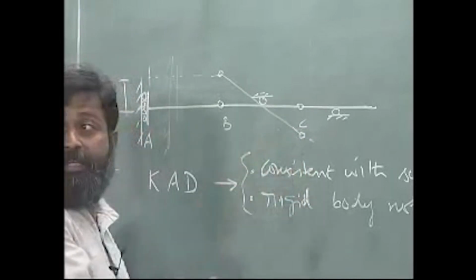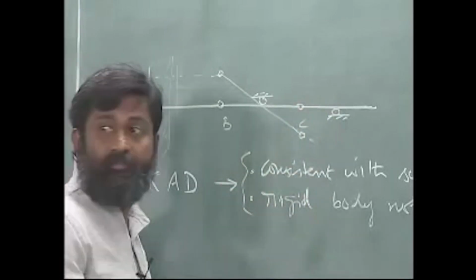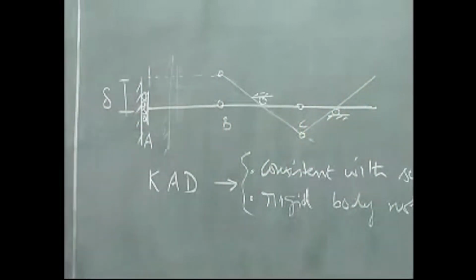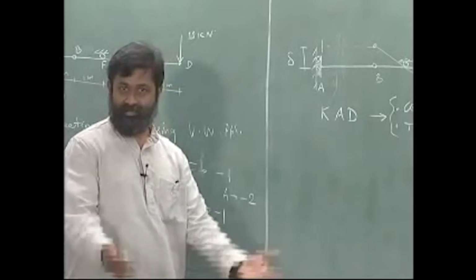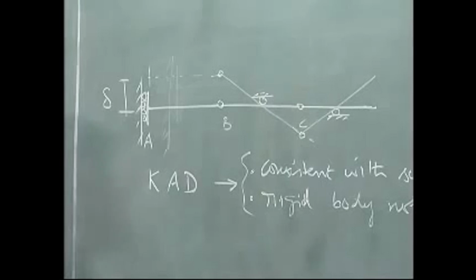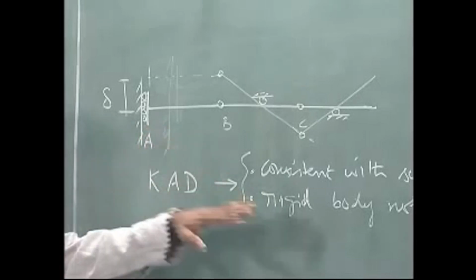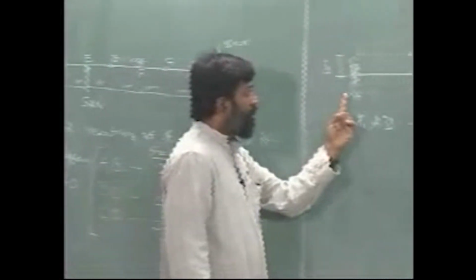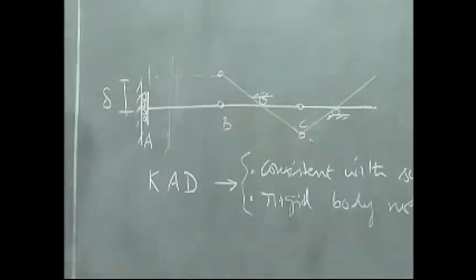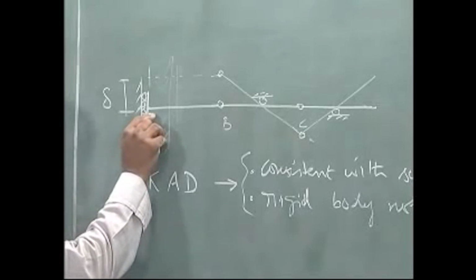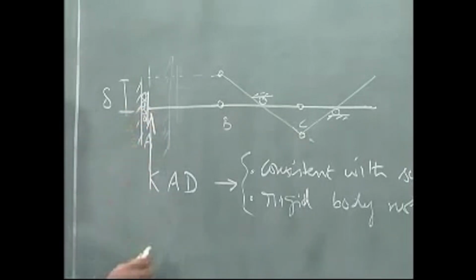Now at point C again this will not allow vertical movement, which means the only way possible is a displacement like this, very simple. Geometrically if I draw it, it will make it simple for me. The moment I know this I have solved the problem. Now let me draw the active forces. Remember I have not drawn any active forces yet; having released the vertical displacement here I have to apply a vertical reaction.